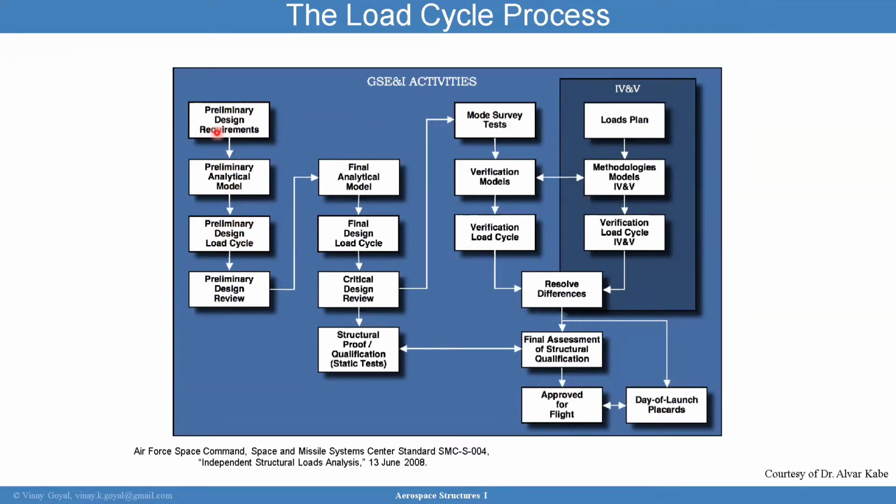So you have your design requirements and analytical model. You want to start looking at some preliminary design load cycles. That will help you define some loads that could be useful when you step into your preliminary design review. I went through these milestones before, but I'm giving more granularity as to where we need to spend some time. It's important to spend time on those loads, because if the loads are wrong, then your final design may be wacky. Maybe it's too thick or too thin. It may not be able to survive the environments that I need for my design.